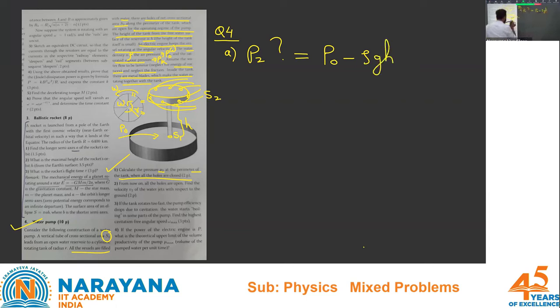Now I have reached the center of the upper disk, and from the center, because of omega, there is centrifugal thrust which will change the pressure parabolically as you move radially outwards, and that term will come out as rho omega square r square by 2.